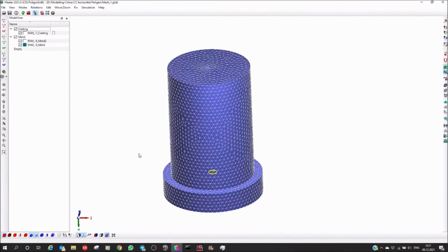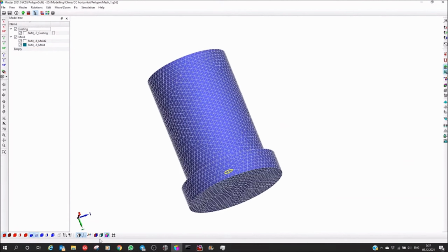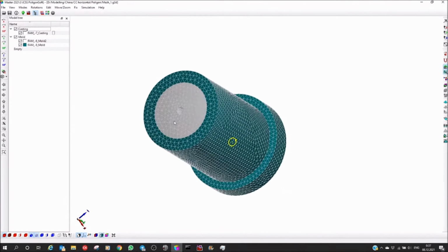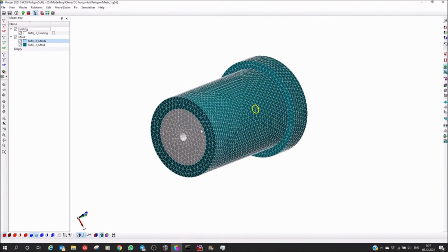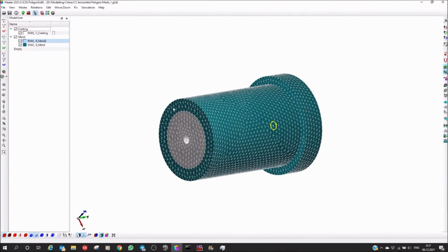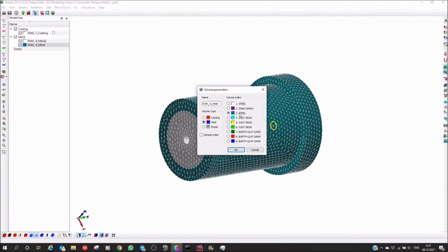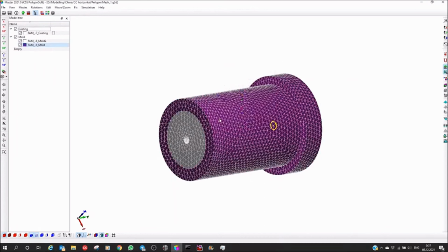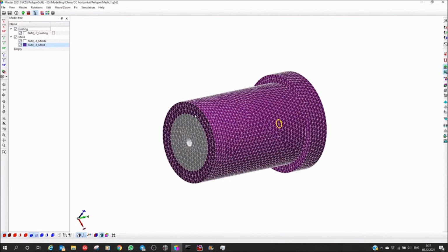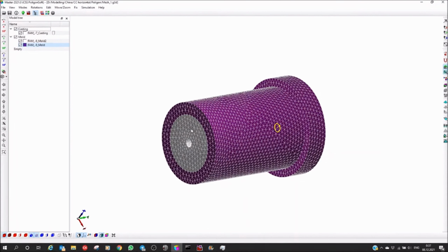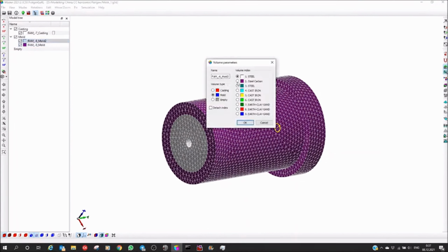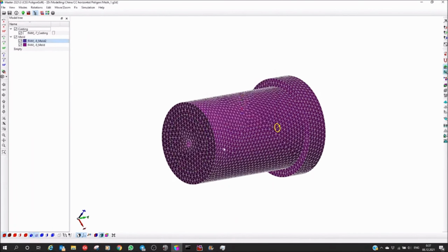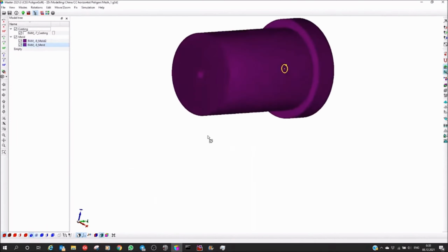And now I can select mold materials and switch on one axis, this axis, and this color is the mold material. If I don't click on this mold building, I see that my steel carbon is here. It's number 2. I will check and press OK. And the color was changed. And I double click here on this particular and select this material and click OK. Now it's okay. I have the wall